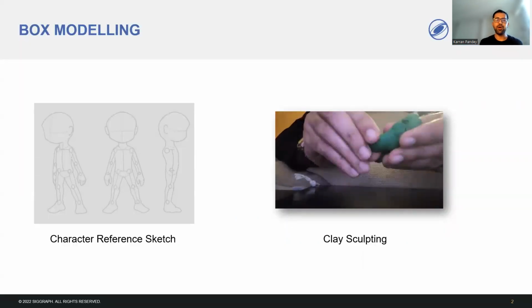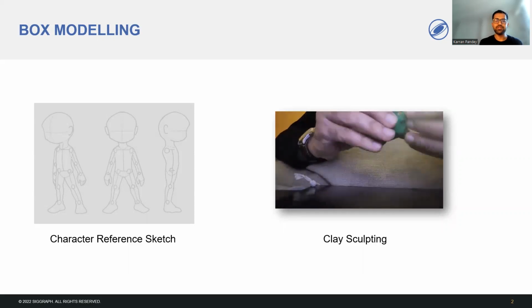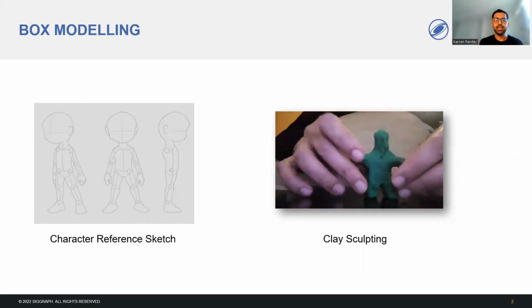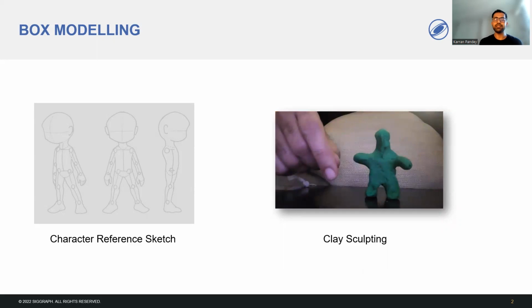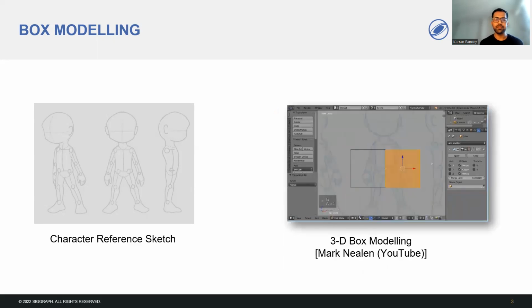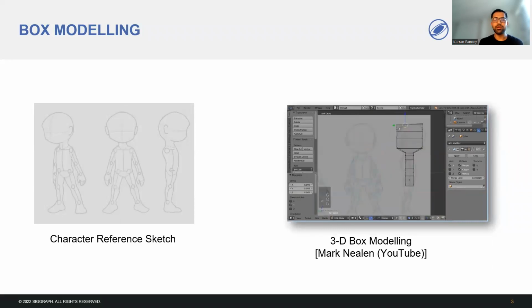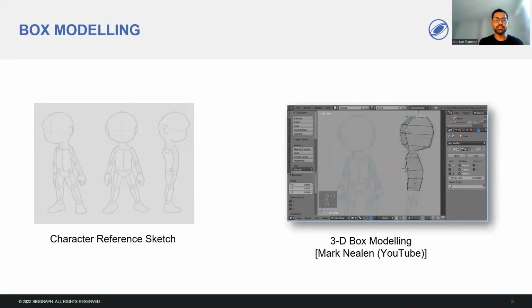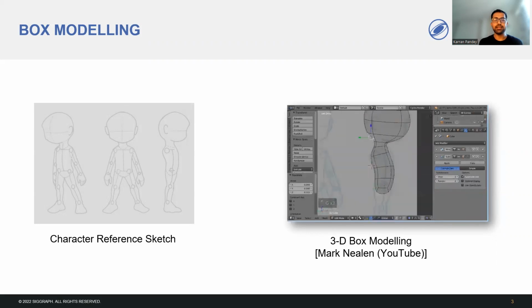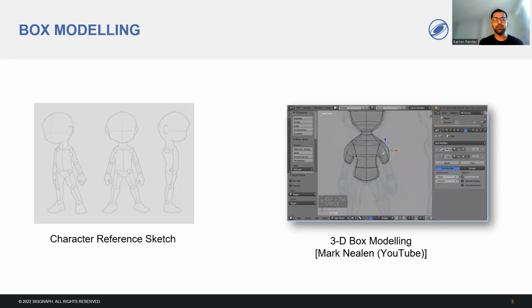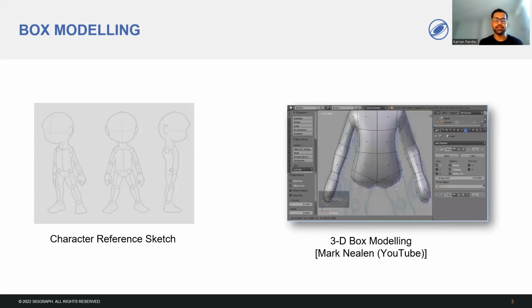Analogous to sculpting from a block of clay, box modeling workflows create 3D models by extruding and bridging parts from a simple starting shape such as a cube. Hundreds of instructional blogs and videos advocate a box modeling workflow to create quad meshes with well-designed face loops that capture a part structure and follow object flow or deformation lines.